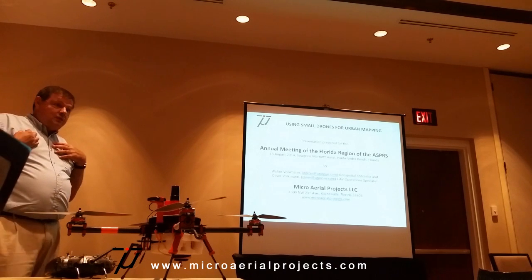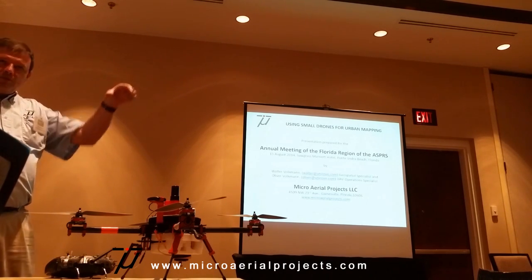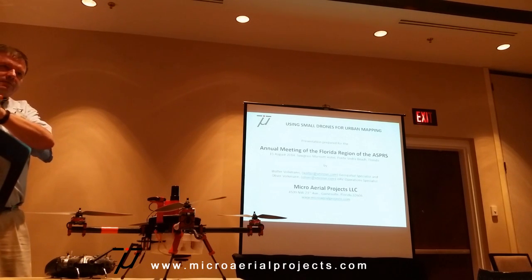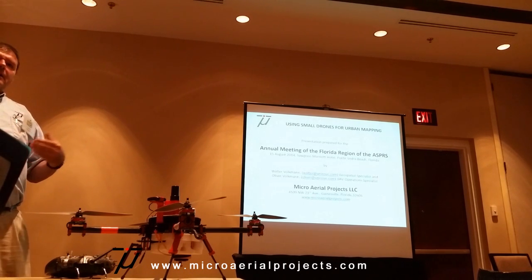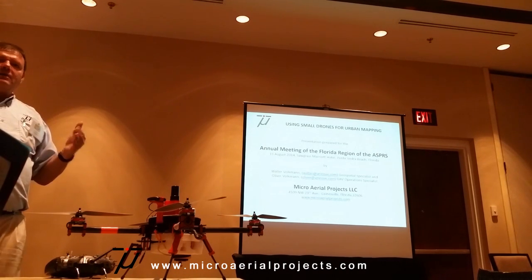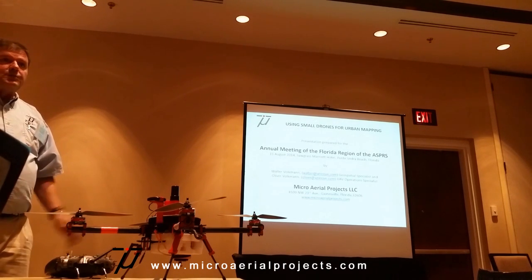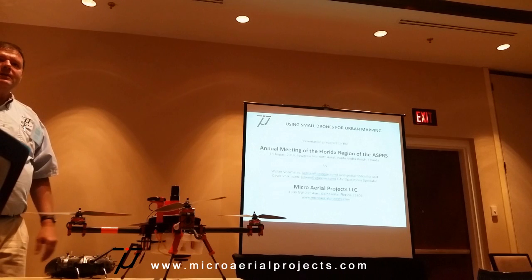So I'm quite confident, since one expects the biggest errors to be on the seam of it, where there's the least amount of overlap, that we did get about 10 centimeter accuracy generally on these models. And that's with minimal control. Only 6 points per 30 hectares is really sparse.